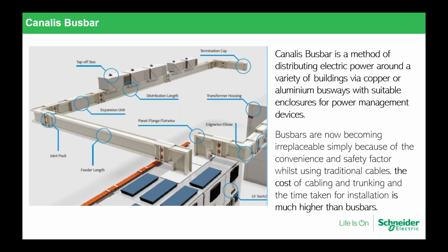As I mentioned earlier in the previous slide, being a method of distributing electrical power, you will find this Busbar everywhere, starting from the low voltage side of a transformer up to supplying the lighting in a warehouse or in a logistics center, because everywhere you need to transport energy, there you need to use the busbar instead of cables. And in some of the slides that I will share today there is a little bit of comparison of why to use busbar instead of cables in applications and so on.